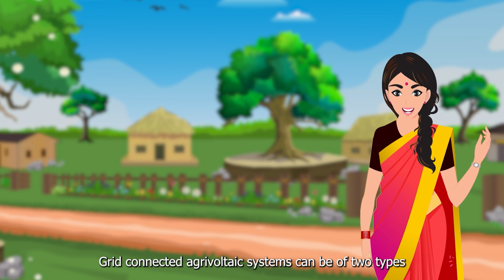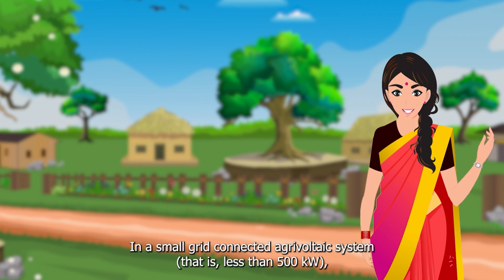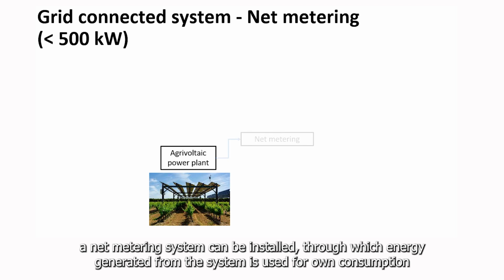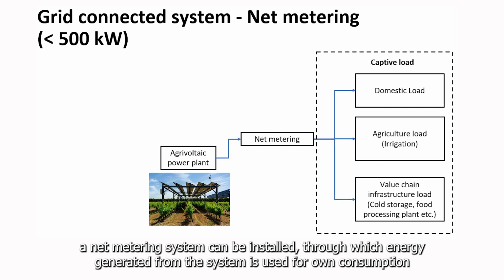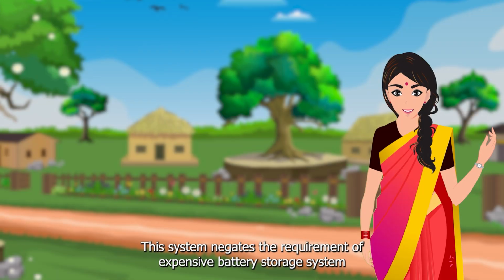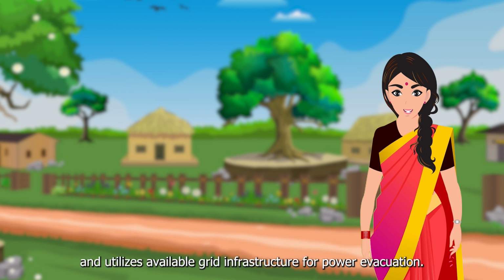Grid-connected agrivoltaic systems can be of two types based on the generation capacity. In a small grid-connected agrivoltaic system, that is less than 500 kilowatts, a net metering system can be installed through which energy generated from the system is used for own consumption and excess energy is sold to the electricity utility at a fixed tariff.